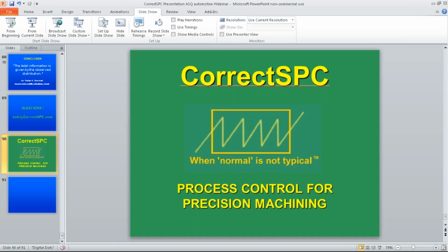And again, this isn't a rubber stamp type of thing. This is going to take knowledge of the process, which includes getting the engineers involved that are familiar with the machines and the materials to understand what kind of variation you can expect. And you do that probably the best by doing a capability study, which, by the way, you do the exact same way. When I do a capability study, I start doing 100% of the parts, but I do them by measuring the high and the low, not by single points.